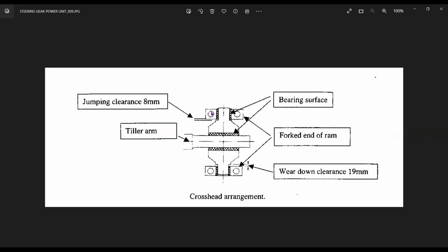Because see, either one mechanism is you have the entire ram which is one part, and you are having an opening in the middle as I showed there. Other way is you have the two hydraulic rams which are connected by bolting mechanism. Means you have got one hydraulic ram with a C face on one side, and one hydraulic ram again with a C clamp side type.